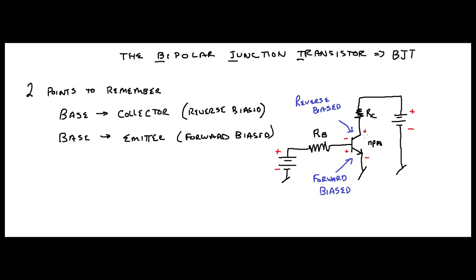But the point is, in operation, if you look at this, we have an independent voltage source here. And if you recall, you needed 0.7 volts across a PN junction for it to conduct. That was how the diode worked. This is basically a diode right here.